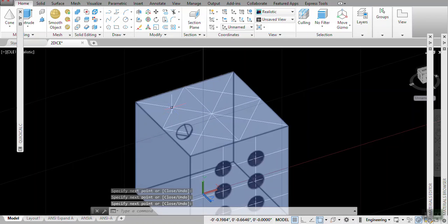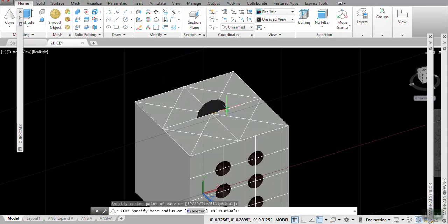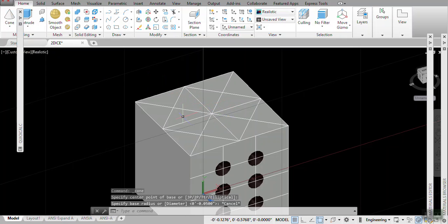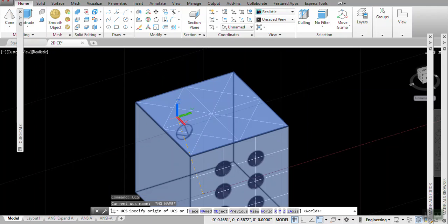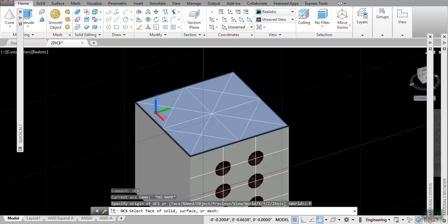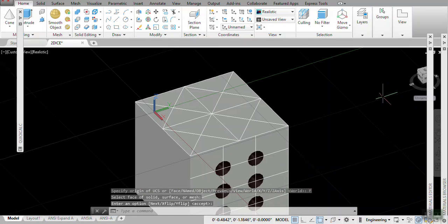That's going to be the indicator, or geometric places, of the centers of the cones that I'm going to locate. So that I have 1, 2, 3, 4, 5 cones. All right, so let's draw the first cone right at the center. Cone command, select the midpoint, and, oh, we forgot, we left something out. What is it? UCS. Type UCS, enter, and we need to enter F, select the face option, select the surface, pick any point except on a line, obviously, enter. Now UCS is located properly.